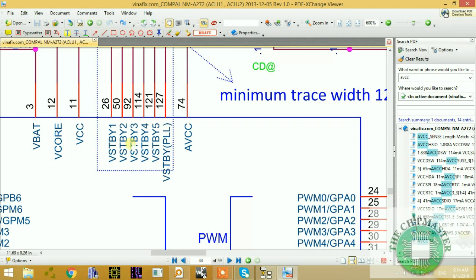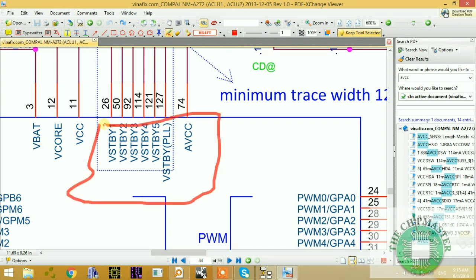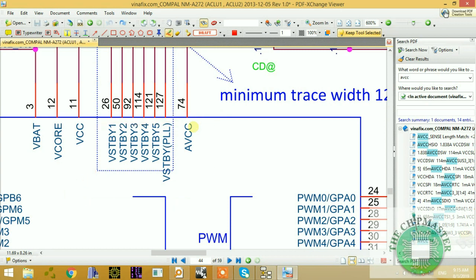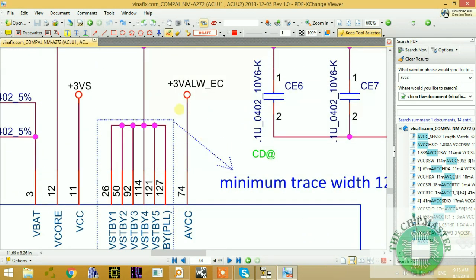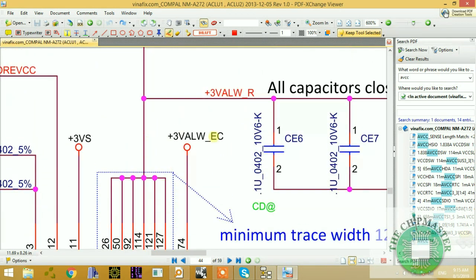So our focus is on these two supplies before we turn on, because if these voltages are not coming, then we can't power the laptop because we have no power, right? So these are your main critical voltages, very important voltages when working with the I/O controller. So suppose this voltage is not coming. Then we know that the board will be dead. It can't power. So we will have to trace where this voltage is coming from.